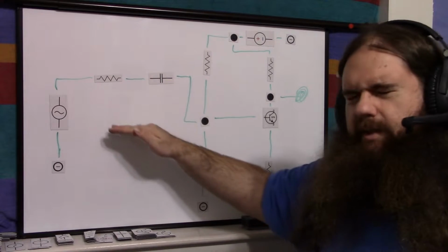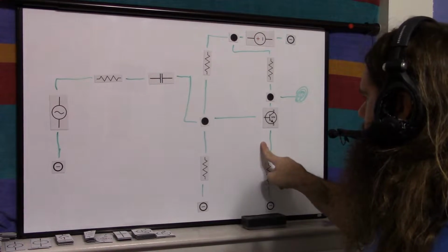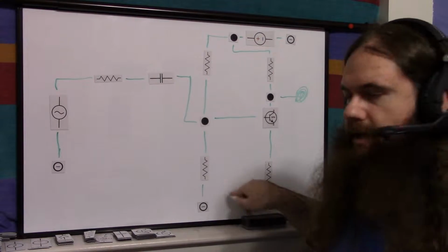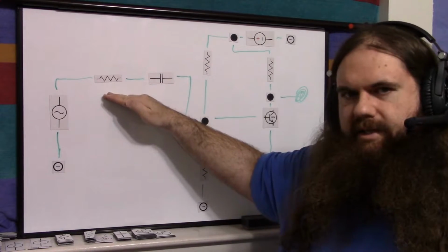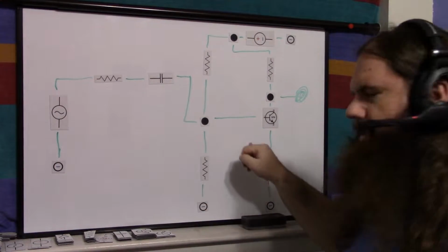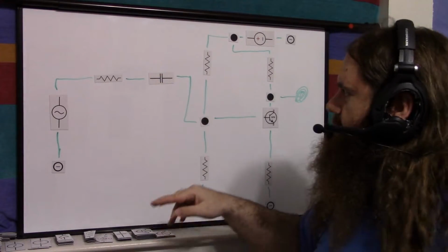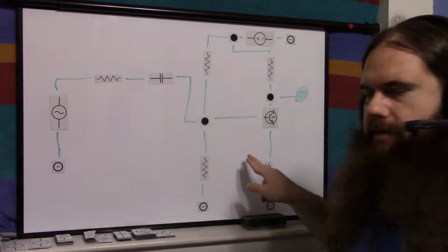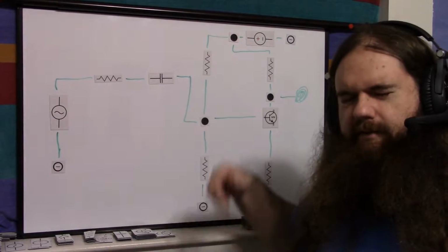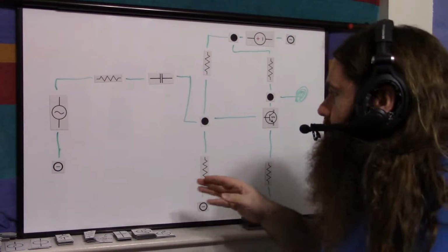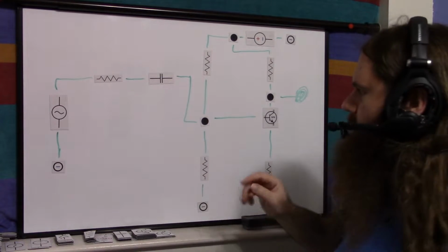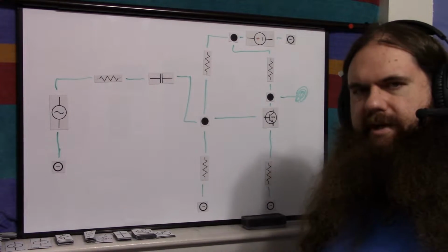up, right? Because normally with a signal at 0, the base and emitter are going to be at 0, and then you move the signal up to 0.7, and now the base is 0.7 and the emitter is 0. And if you move it up to 1.7, then the base is 1.7, the emitter is 1. And if it's negative, of course, it's still off until you break your transistor, which is why we need this wiggle room. But what if we could just put the transistor higher?